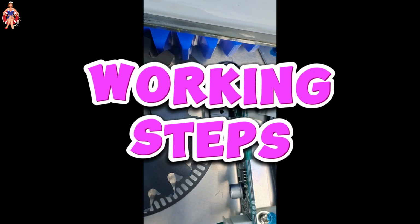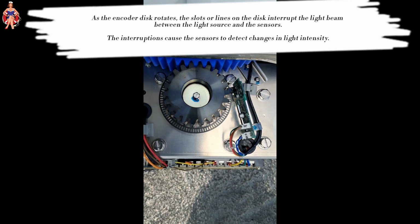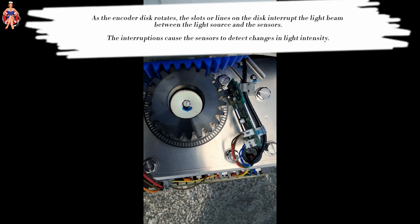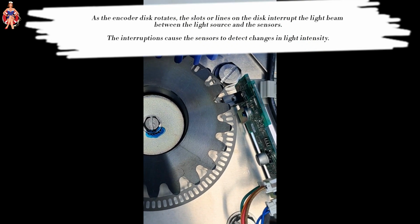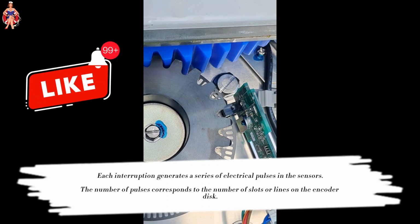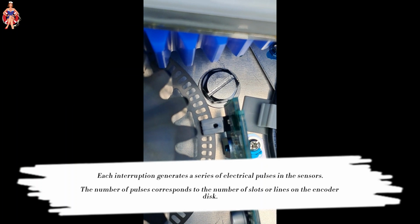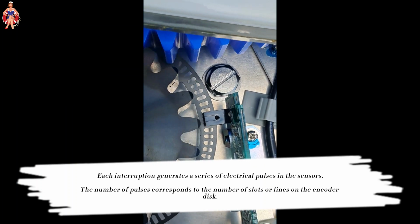Working steps. As the encoder disk rotates, the slots or lines on the disk interrupt the light beam between the light source and the sensors. The interruptions cause the sensors to detect changes in light intensity. Each interruption generates a series of electrical pulses in the sensors. The number of pulses corresponds to the number of slots or lines on the encoder disk.